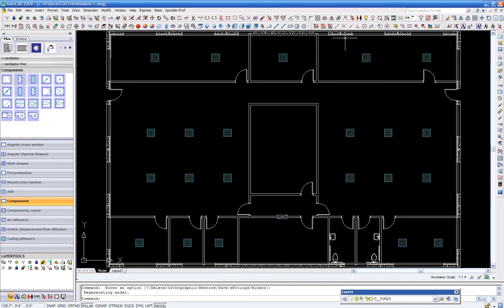We will now begin locating the center line from the center line of our fire damper by using the AutoCAD Commander line. We are now showing the center line of our supply duct on the drawing. We continue extending our center line to its selected location. It is important to pass beyond the last diffuser with your duct center line.